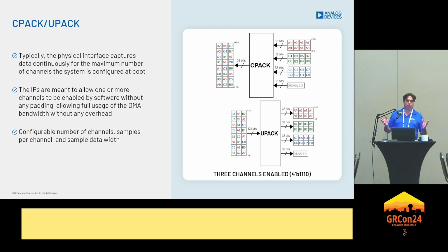For example, if you have enabled 16 channels, you're running out of memory bandwidth over the transport medium or in the storage. You just disable 15 of them, and you only have one channel, and now your bandwidth bottleneck is gone. Of course, you have far fewer channels, but these cores do this on the fly. They are independent IPs, but they're controlled through the transport layer. So the transport layer's channel enable is just an output and it goes to an input on that core.